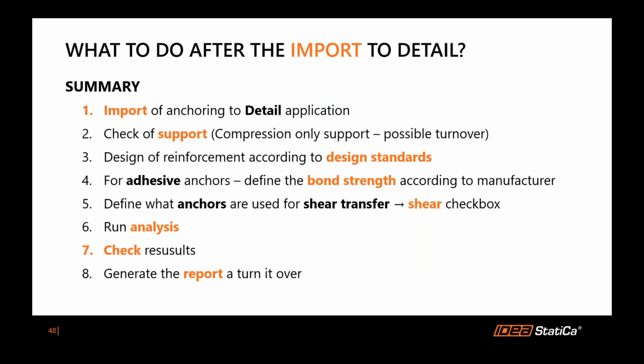So the first step is to model the anchoring in the Connection application and export it to Detail. There, you should always check the support, and if it's a compression-only support, you have to be aware that you need to check the possible turnover as well. Then it's always mandatory to design the reinforcement.